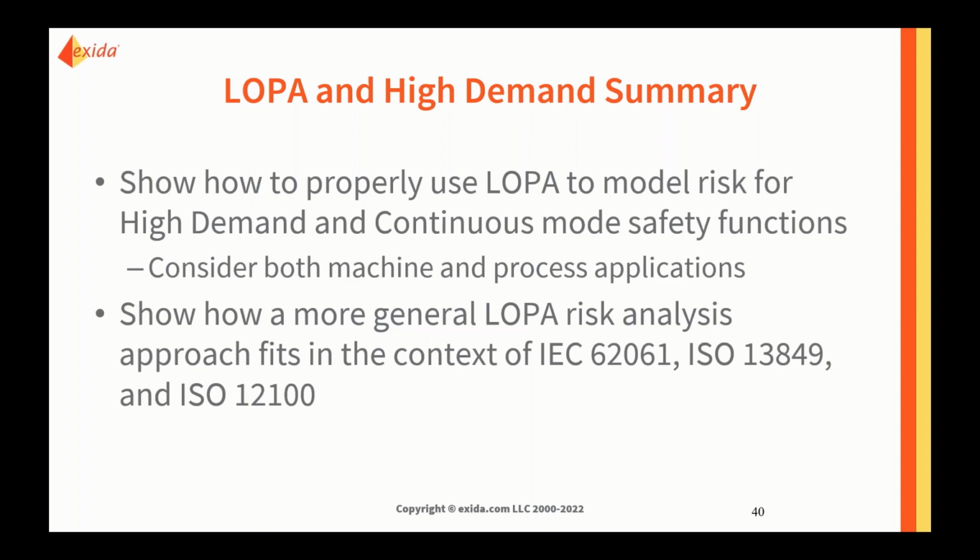Now, what you can look at in the extreme, and I'll try and answer this briefly. Let's say you have a high demand safety function which fails once every 22 years. And we consider the difference between a demand every 10 minutes and a demand every 2 months. The actual difference in accident frequency is only going to be once every 22 years and 10 minutes versus once every 22 years and 2 months, which is actually a relatively small overall frequency difference, and therefore fits that modeling of the safety function as an initiating event failure.